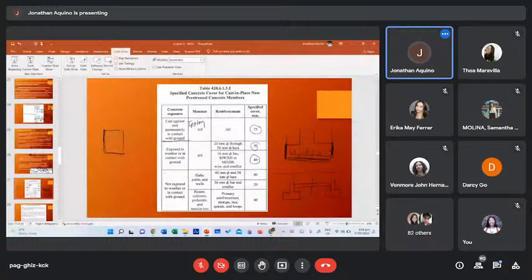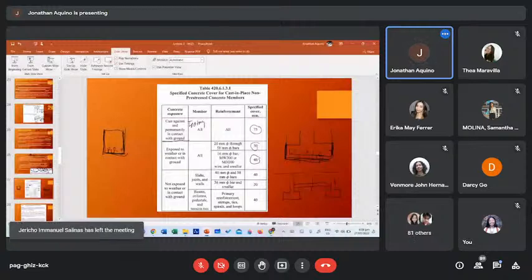So ibig sabihin, control pa rin yung concrete cover niya, kasi nami-maintain natin dito yung tinatawag na spacer block para ma-maintain natin yung height. But dito, in this case, although meron tayong spacer block, there's a tendency that during pouring, lulubog konti, kasi kung lupa lang ito, lulubog konti yung bakal mo. Kaya mas malaki yung prescribed or specified cover pag permanently in contact with the ground and in contact with the ground.